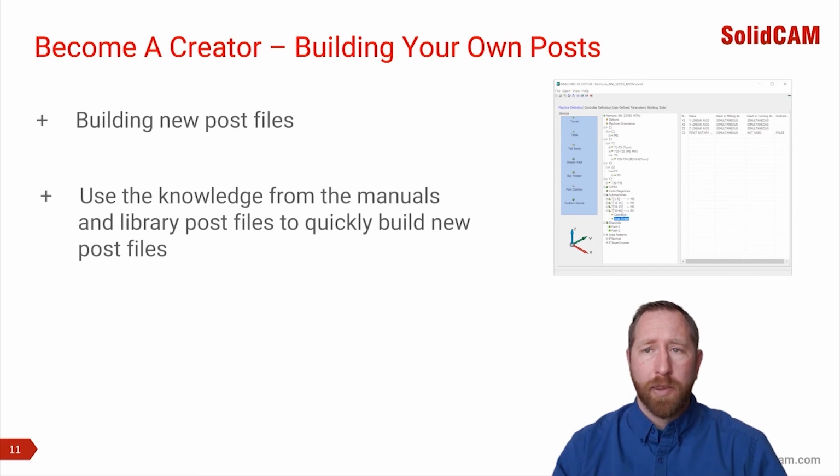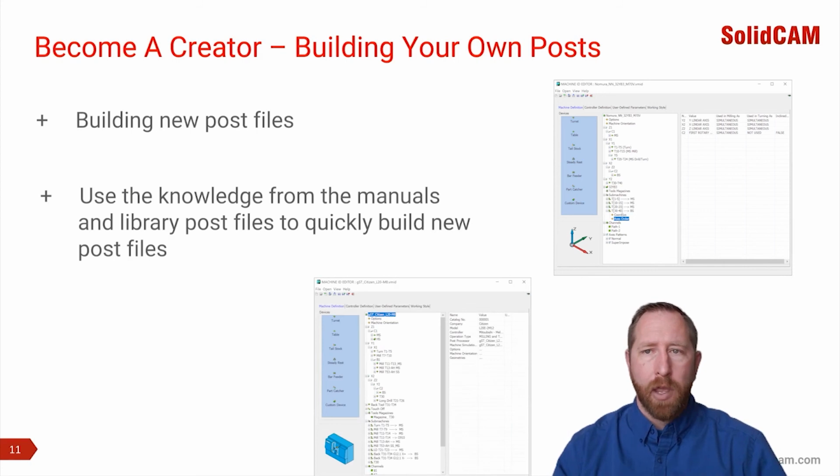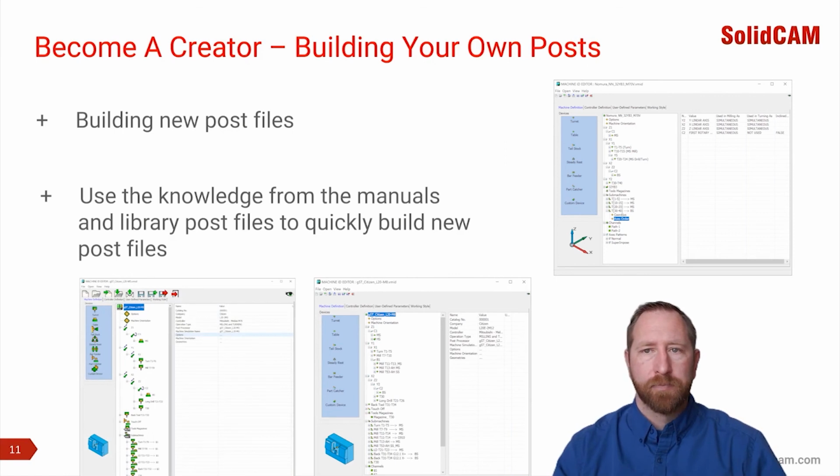A lot of times you will find that within brands, a lot of models will have very similar kinematic structures. For instance, if you need to build a post for a Citizen L20 Type 5 and you see an L20 Type 7 in the library, you can take those files from the Type 7 and use them as a template. Verify with the manual as to what the necessary tool station positions and capabilities are, and amend the VMID file accordingly. This can be a huge time saver over building these files out from scratch.